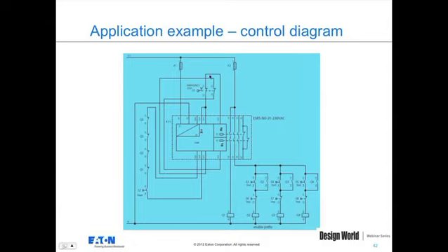First off is the e-stop up here. So this is our two-channel e-stop. So one channel is here between S11 and S12. The other channel is down here between S21 and S22. So again, these two channels are going to have different voltages on them so that it can detect if there's a short circuit between the two channels.